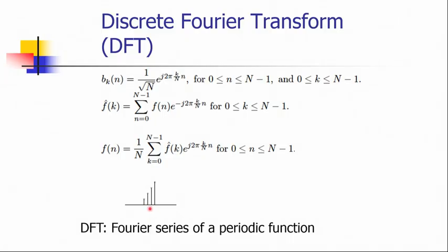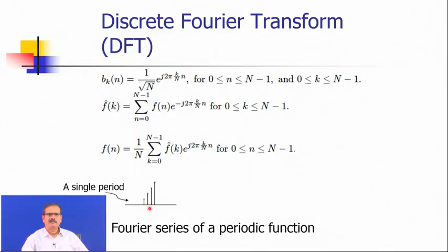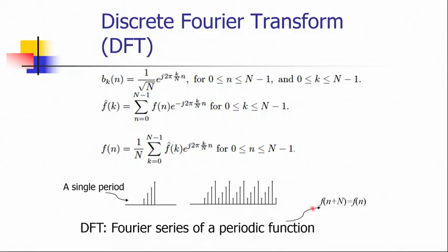So, a periodic extension of this signal could be in this form, that means it is repeated. In a periodic function with a period capital N, this property needs to be satisfied: f[n plus N] should be equal to f[n]. That is satisfied, as you can see here. Here the value of capital N is equal to 4, so after every 4th sample it is repeating the same value.